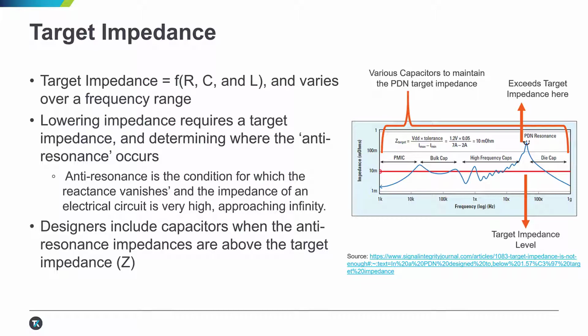And every PDN has a target impedance that's set around the operational frequency in the ideal state that's usually included within the design stage, and all components have to operate with minimum impedance at those frequency ranges. If the target impedance increases, then usually designers will include different types of capacitors to lower that impedance, with the goal of not affecting the overall PDN's performance.